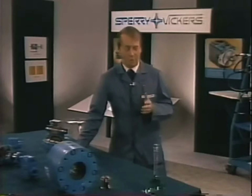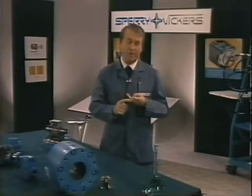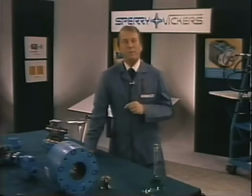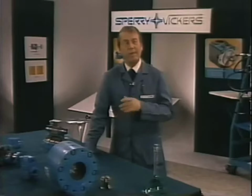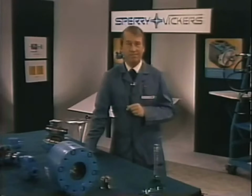We did it with only 3 valves: a directional control, a flow control, and a pressure control, also known as a relief valve. You've probably already realized that these same components would enable a cylinder to function in essentially the same way as the motor. In fact, these components are the main ingredients of even the most complicated systems.